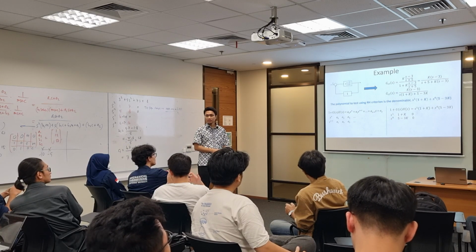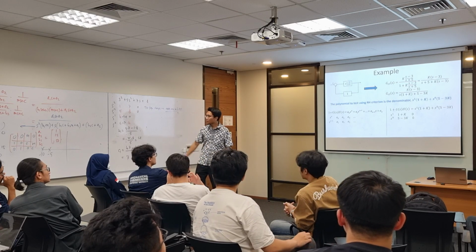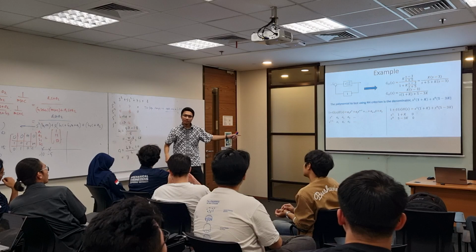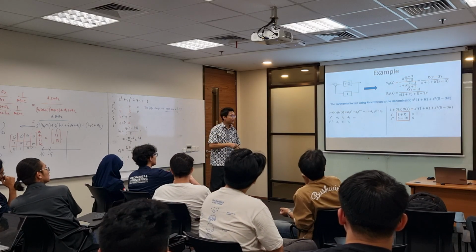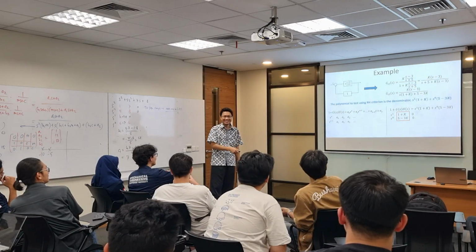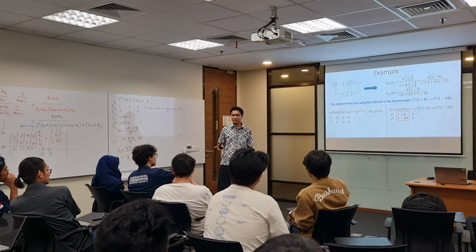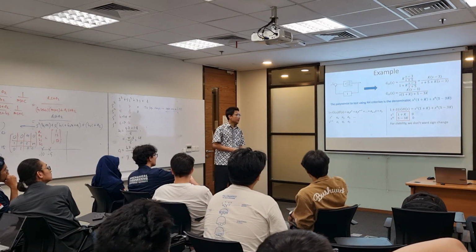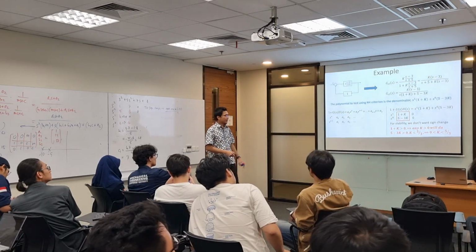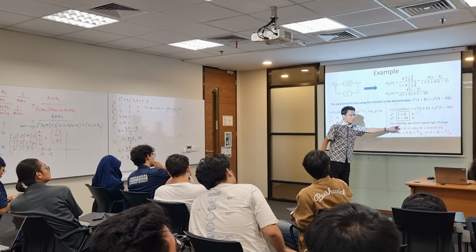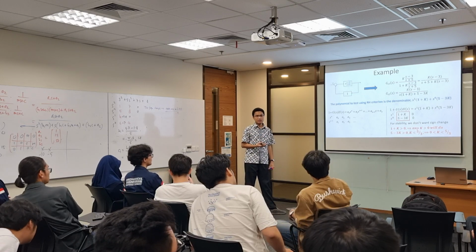That's the Routh table: 1 plus k, 5 minus 3k. Do I need to compute b1 and c1 here? No, that's the only thing that we have. Don't force yourself to compute s to the minus 1. If you want it to be stable, then we don't want a sign change. I can say stability because I am checking the denominator of my closed loop transfer function.